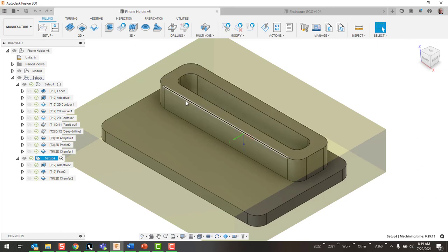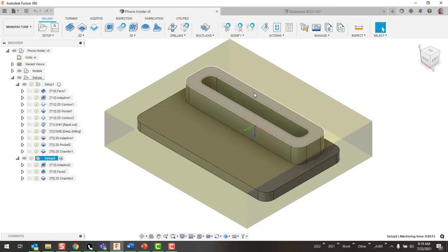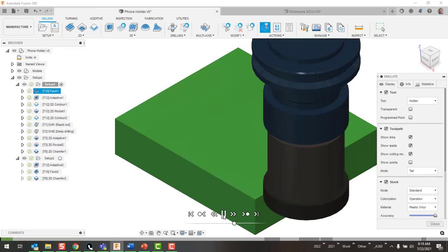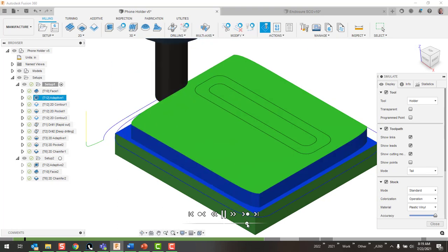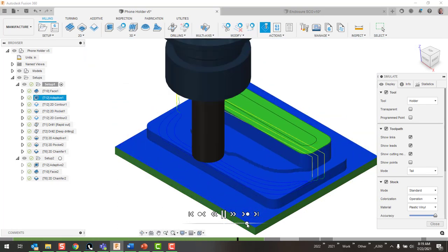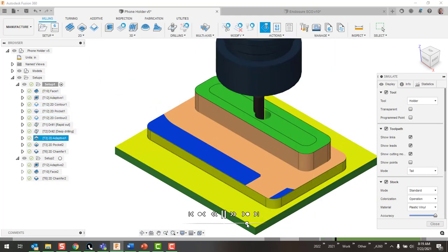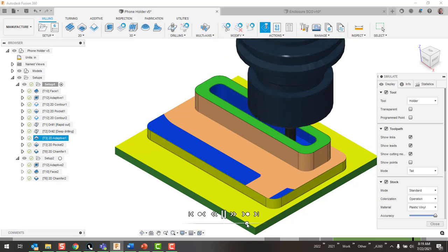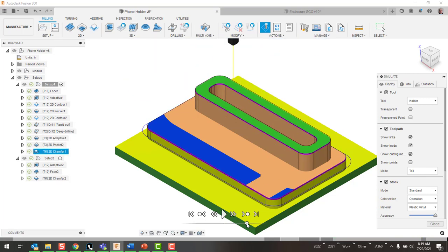This is the default data set for that, where we basically create a very simplistic part here, and we can then create the toolpaths that would be needed to cut this out of a piece of stock. You can see here, I'll speed up the animation, so it's going to do a couple different types of operations there. And then if you do have a machine shop, this would be the type of thing that we could post-process, and the students would be able to take that G code off of this example, and put it on a machine out in the shop and be able to recreate this component.